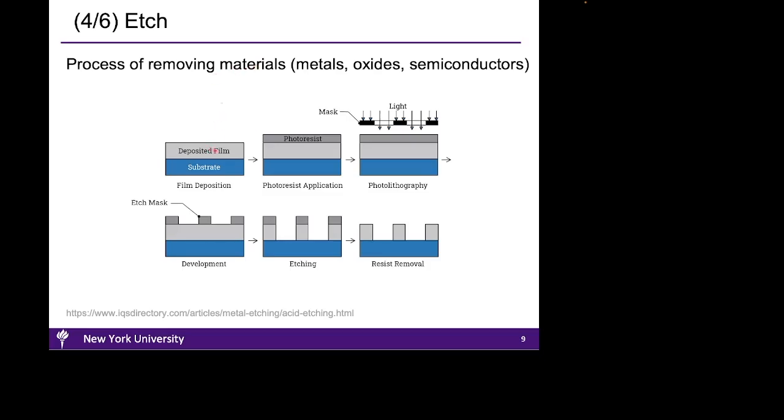Once a film is deposited onto the substrate, the desired features are being printed through the lithography process. The patterned photosensitive resist serves as an etch mask where it is protecting the underlying deposited layers. The unprotected regions, however, are removed through the etch process, which subjects these regions to controlled chemical and physical attack. We'll review the etch process in a later video.